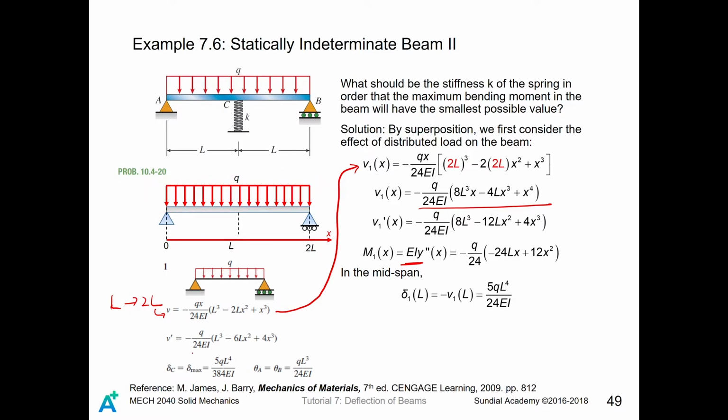So still, once you get the deflection curve, you will get everything you want, because everything is just like a necklace. Every marble is interconnected by some relationships. So one thing you have to bear in mind is that still you cannot forget the EI in front of the moment. Okay, so when I do this PowerPoint, I always forget about it, and it can be a very fatal error when you are doing calculation.